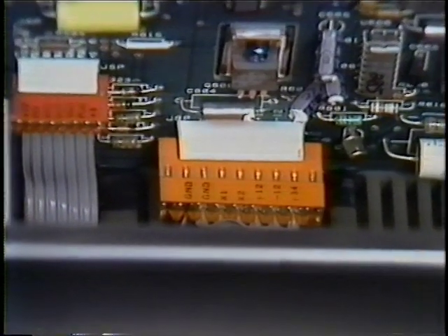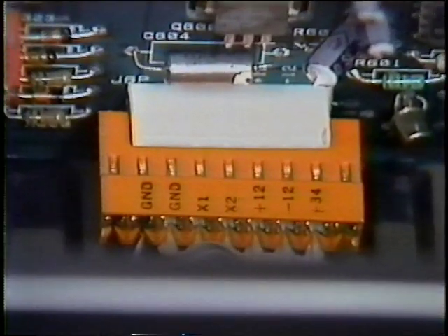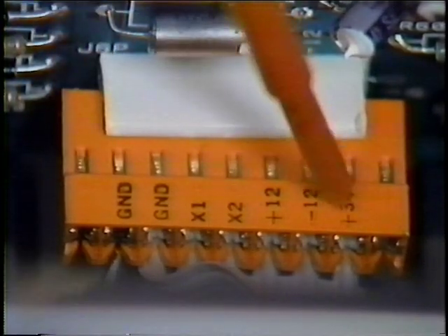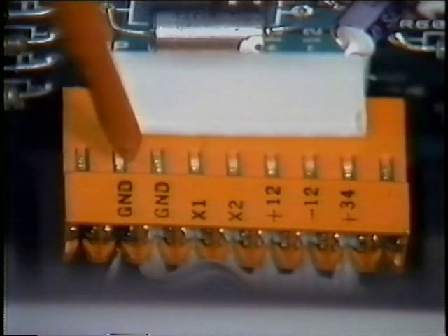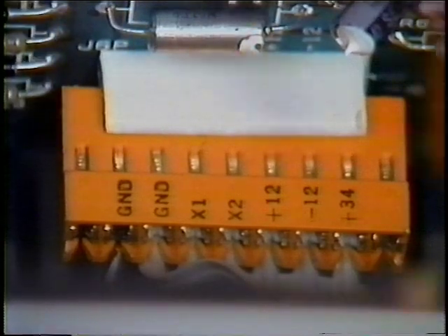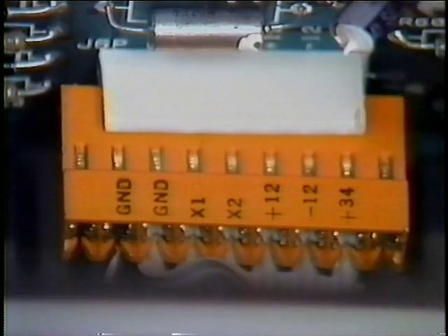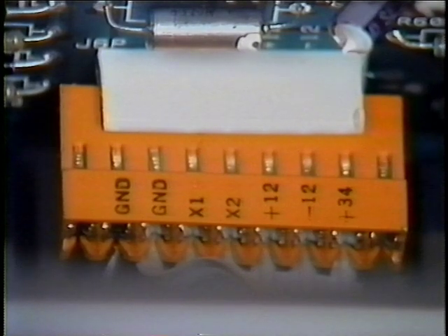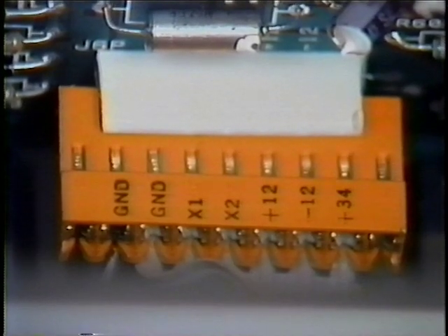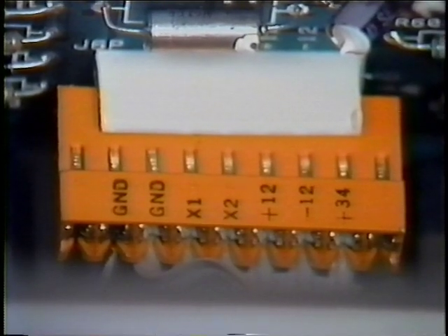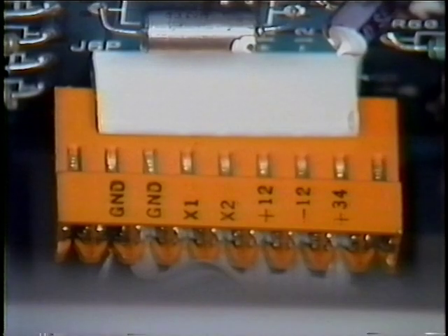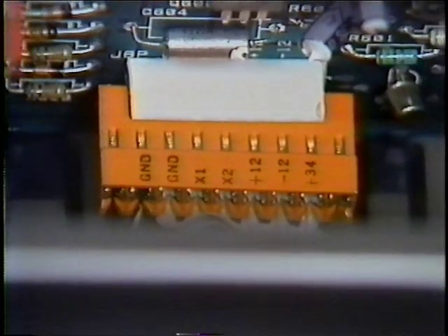This is the power supply connector J6P. This connector also has a blank pin on each side of the connector. Because of the time required for the 2 large capacitors in the power supply to discharge, it is necessary to wait for 2 minutes after turning the machine off before reconnecting the power supply connector. Not waiting for the capacitors to discharge can cause damage to the printer board.